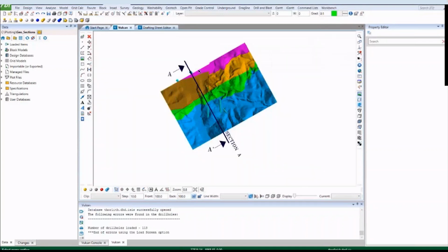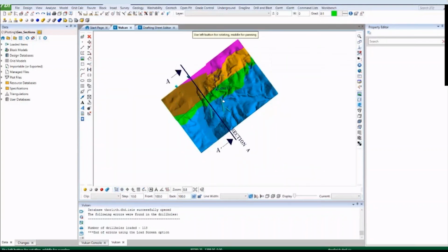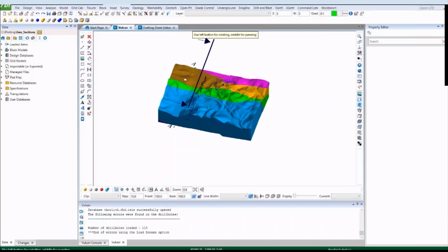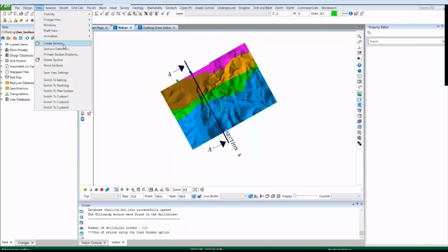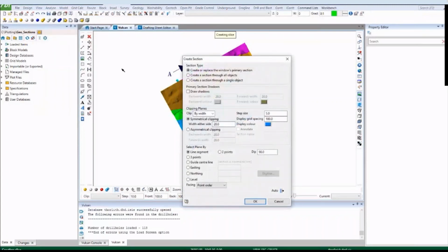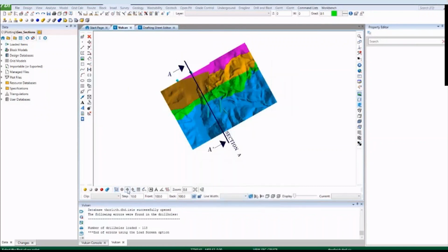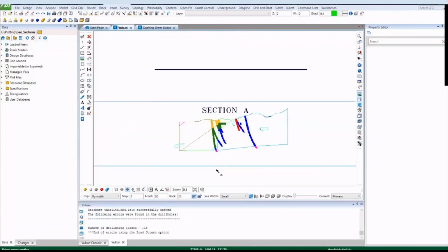So here I'm switching my background to white. I got some drill holes on my screen and I got some triangulations on my screen, and I will explain the white background in just a second. I simply hit the A key on my keyboard to get that white background. We're getting into a cross section, basically setting up my views for Plot All Wizard.